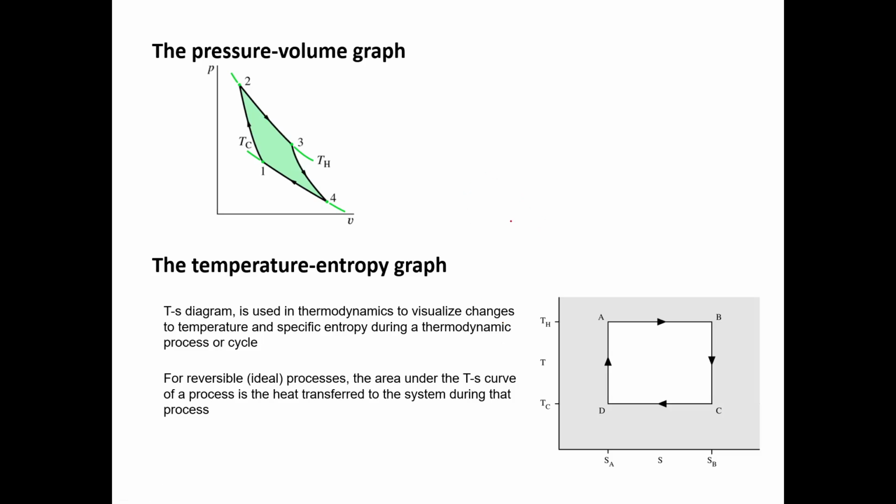So that is the PV diagram that I have drawn earlier, right? So basically 1 to 2 is adiabatic compression. So here you have W in. Then in this case we have W out. At the same time we have Q in. So this is isothermal expansion. Then we have adiabatic expansion, also with W out. There's no Q involved here, and in here we have W in.